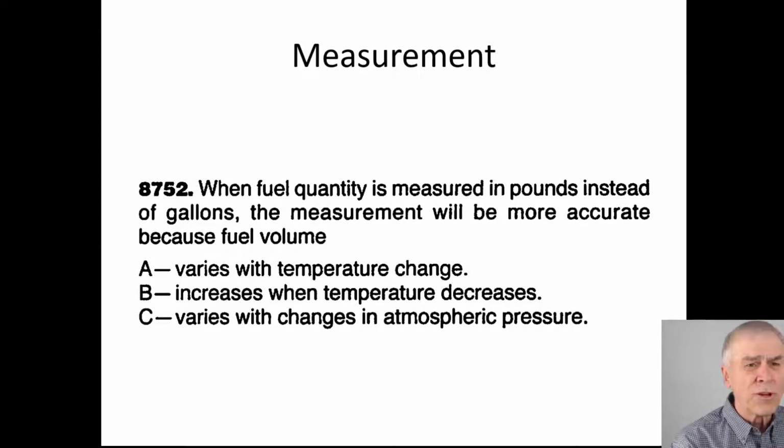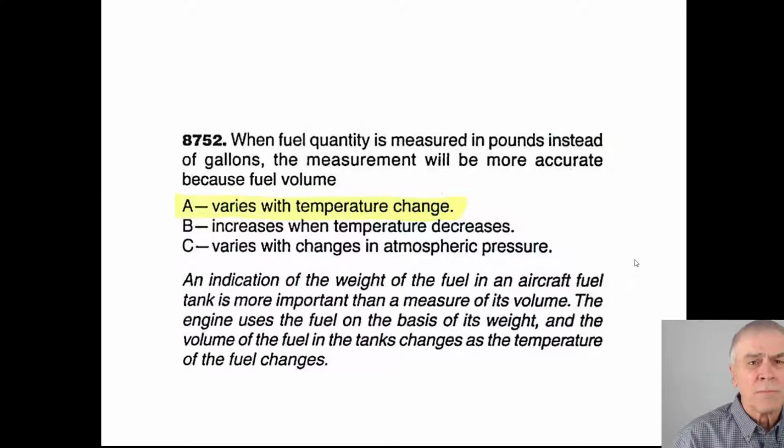Let's take a little closer look at number two. Does fuel volume increase when the temperature decreases? Well, when it gets colder, we saw that it contracts a little bit more. So actually, fuel volume decreases when temperature decreases. So A appears to be the correct answer. The engine uses the fuel on the basis of its weight, and the volume of the fuel in the tanks changes as the temperature of the fuel changes.